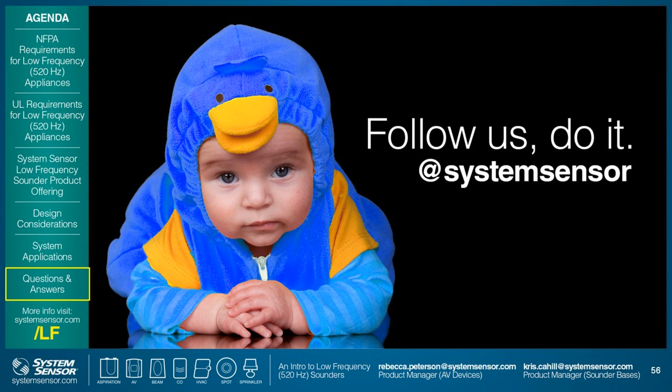They're asking a question about low-frequency sounder bases and being synchronized. Can low-frequency sounder bases be synchronized amongst each other? They can be synchronized amongst each other, absolutely. And with the B200S-LF, they can be synchronized with System Sensor AV devices as well. Okay, all right.